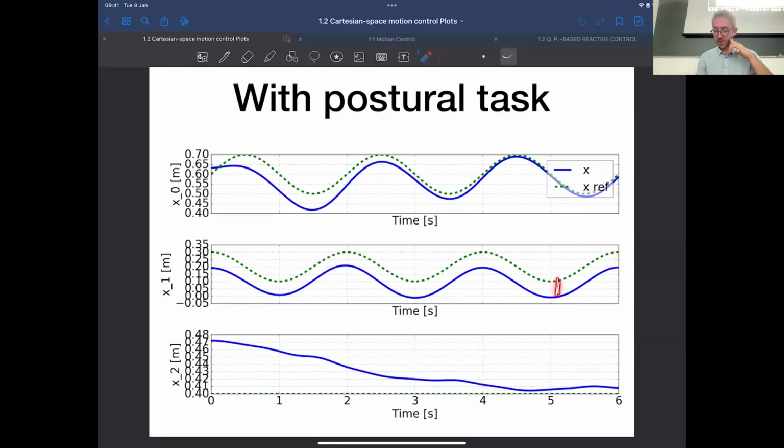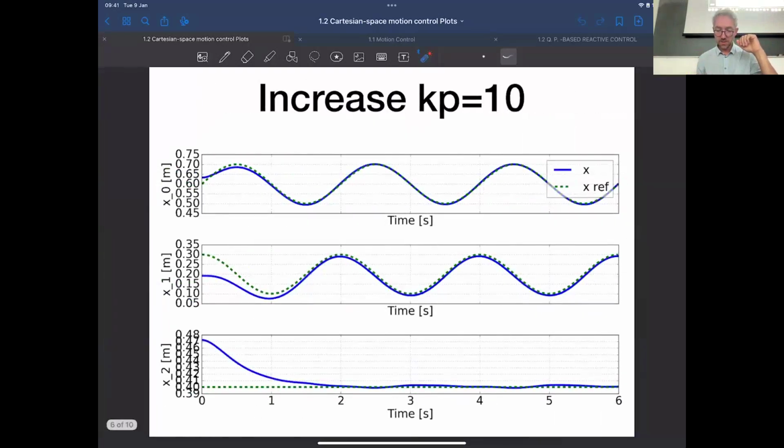So the error is probably being reduced, but it seems basically constant. It's behaving better on the x-axis, because we can see that by the end of the simulation, the tracking error is relatively small. So here, the first thing I would do is to increase the gain to see if that helps getting on the trajectory faster.